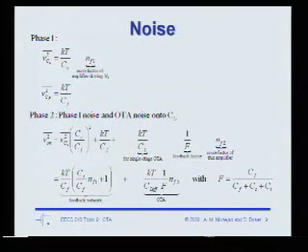And so at the end of the day, for most cases, the same thing happens. You get kT over C times some factor, and that's because the transfer function of the filter tends to do the same thing. So all you need to do is take into account the relative location of the bandwidth relative to the resistance of the transconductor, right? So if the bandwidth is 10 times smaller than the actual transconductance, let's say resistor, then you get 1/10 the noise. If it's 10 times bigger, you get 10 times the noise, right? Okay. So this intuition is very powerful because it lets you very quickly calculate the noise.